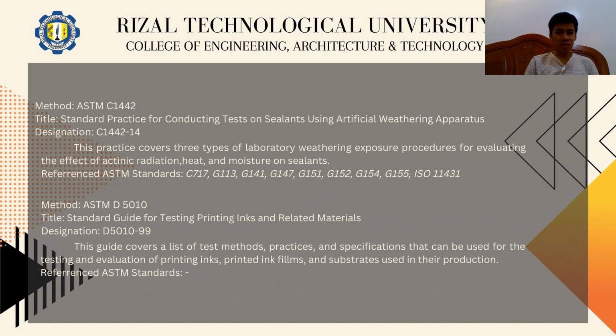This practice covers three types of laboratory weathering exposure procedures for evaluating the effect of actinic radiation, heat, and moisture on sealants. This practice determines the effect of actinic radiation, elevated temperature, and moisture on sealants and their constituents under controlled laboratory artificial weather test conditions.